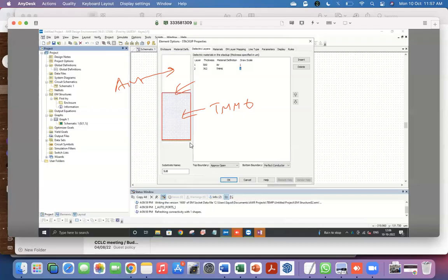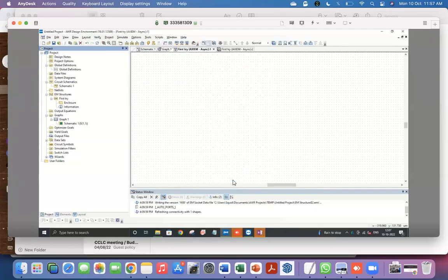If you want to do a strip line, then this air layer will also be replaced with the same dielectric, right? You would think that the circuit board is continuous, so you just have to define one dielectric block, but then I will not be able to put the metal in between. Okay, this is not physics or engineering, this is software. This is how you define the system. So you now have these things defined. Hit OK. And I come to the enclosure, and I can now start drawing.